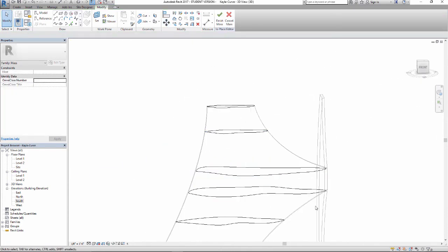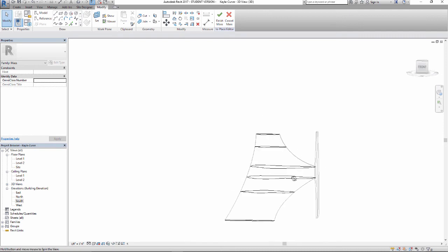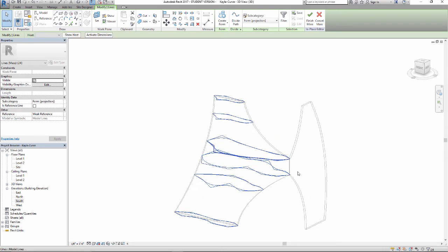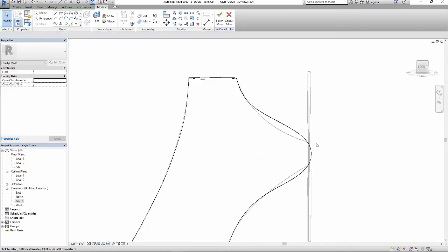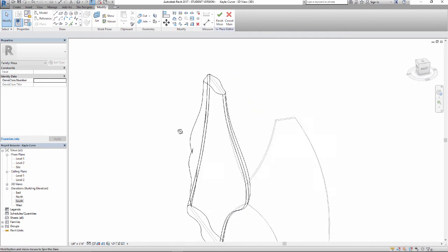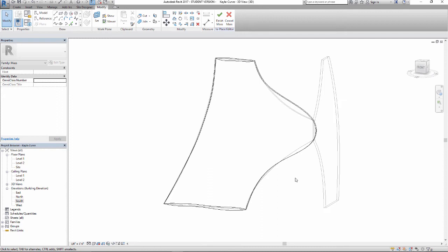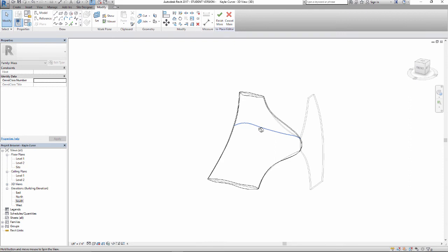So this is still going to curve out, because what Revit is going to do, what the lofting command is going to do, is look to make the smoothest possible line across this edge. And that's simply a nature of how lofting inside of the program is going to work. To get that really precise level of control, there's a couple of things that we could do. We could come back and actually subtract something out, but that's not going to give us that sort of consistent roll. This is honestly one of those things where I begin to talk with students and say, how much does that curve really matter to you? Does it need to be that exact shape?